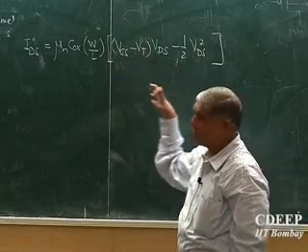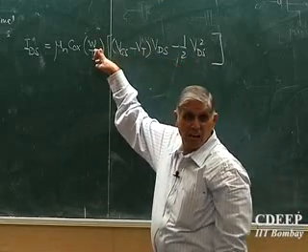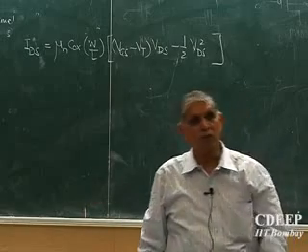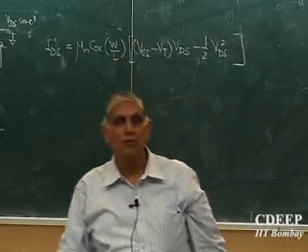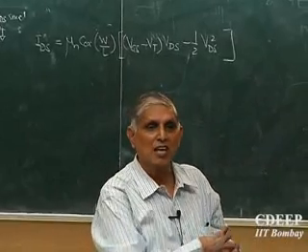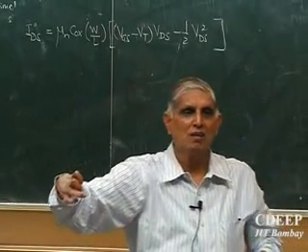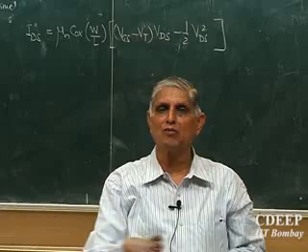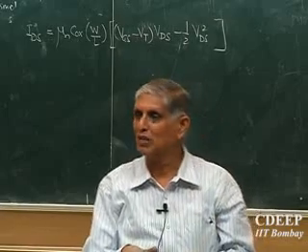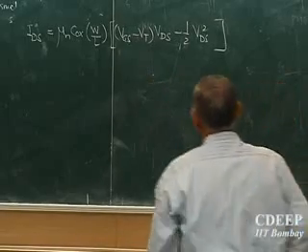These are fixed, VT is fixed. Size, W by L: L is normally fixed by technology but width is my choice. So a transistor with larger width means larger currents can be drawn. Larger width means another issue will come. What will the larger width issue be?